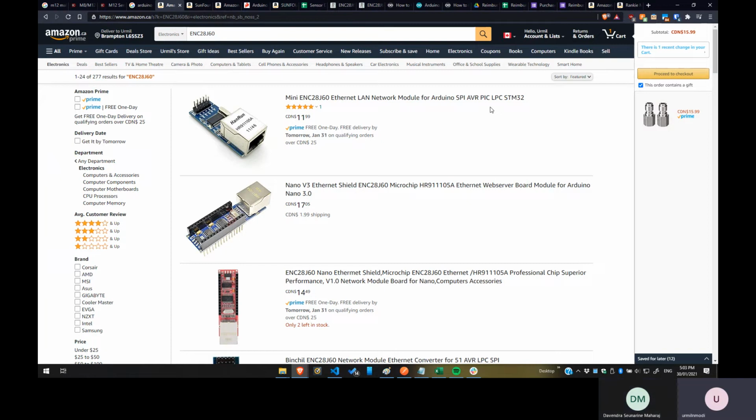Okay. The output range they give us in terms of voltage is the same, but because it's measuring from 0 to 500, your precision is a lot less. Our output max is going to be I think 150. So if you get something within that range, then your precision is better. You're scaling essentially. Right. Okay, so I'm guessing these are already tested, so we can just use them.